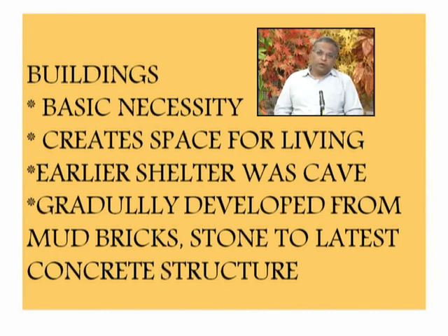Then another very important aspect is that you may select the type of the building based on the substrata, meaning the soil available. If hard soil or hard rock is available, you can construct a load-bearing structure or a heavy building on that. If that much bearing capacity soil is not available, you have to construct the building accordingly. So foundation is a very important point to be kept in mind at the time of selecting the type of the building.